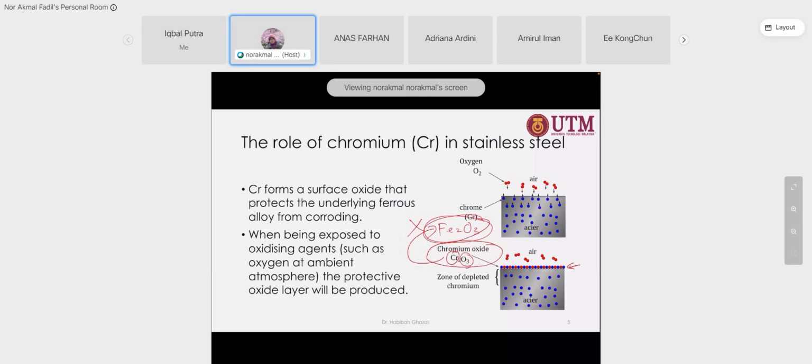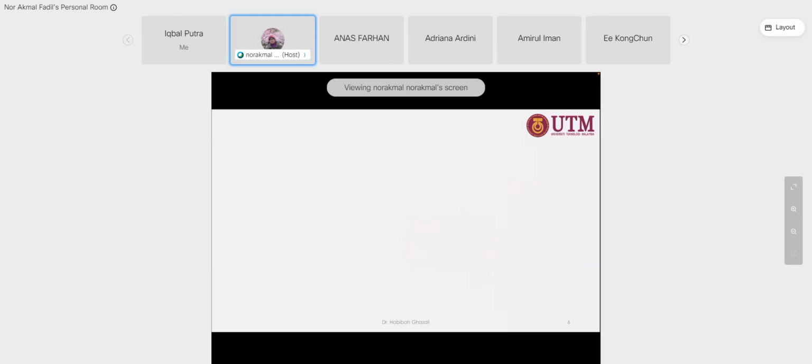But imagine stainless steel. It is a shiny light surface. The shiny light surface of stainless steel is actually the chromium oxide. What you can see, a metallic, very shiny surface, is actually chromium oxide. It is an oxide also. Iron oxide and chromium oxide both are oxides, but they are different in terms of characteristics. One has very poor properties, one has very protective properties. So we need to choose the right alloying element to make sure that it serves the purpose.